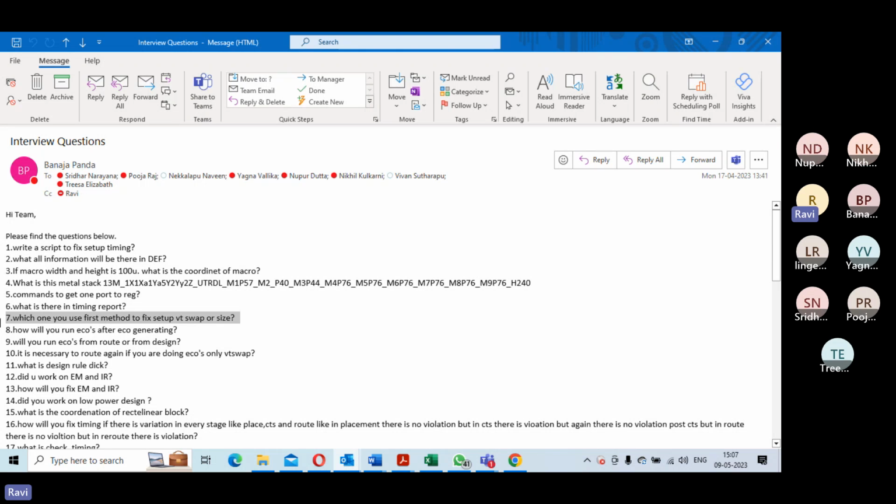But prefer to take ECO by netlist so that you are able to read both the ECO netlist and your principal netlist. You can actually do a diff and then consume and place those cells appropriately. This is how you will address the functional ECO. I prefer ECO by netlist, but you can do ECO by file also.